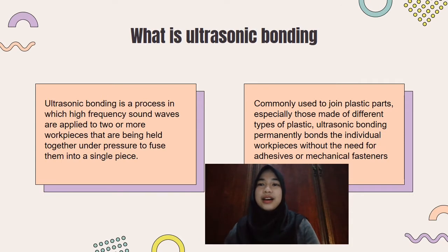And in IC fabrication, ultrasonic bonding is used in the wire bonding process. Wire bonding is the method of making interconnections between an integrated circuit or other semiconductor device and its packaging during semiconductor device packaging. Although less common, wire bonding can be used to connect an IC to other electronics or to connect from one printed circuit board to another.